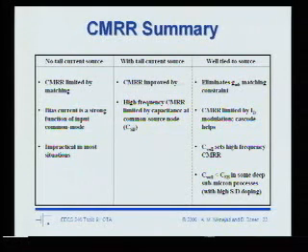If you have the option of AC coupling, you could hold the common mode constant with DC biasing circuitry and then AC couple, and that would be okay. But if you had that privilege, you wouldn't worry about common mode anyway. So if you are worried about common mode, you have to think about it. For most situations, this is really impractical.